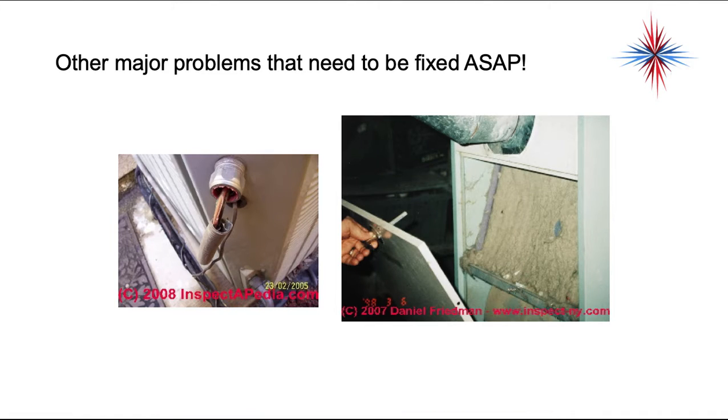Okay. Keep an eye out for other safety issues. The picture on the left has nothing to do with airflow, but it is a problem because you now have a sealed tight exposed wiring. But the one on the right is the one I really wanted to show you, okay? You have a filter in the back of an oil furnace that looks like it has never been changed. You can actually, if you look close on it, it's actually pulling in.